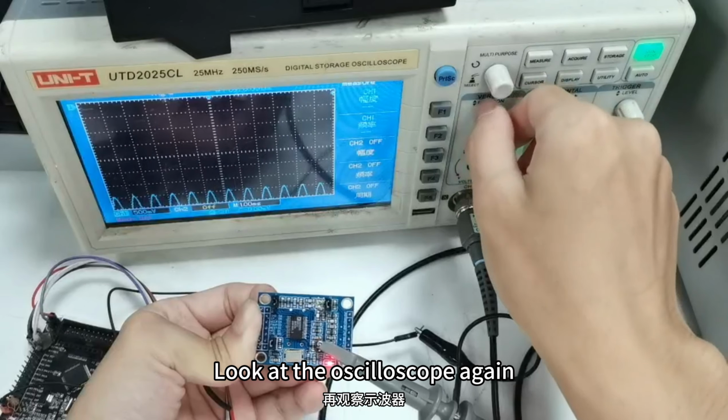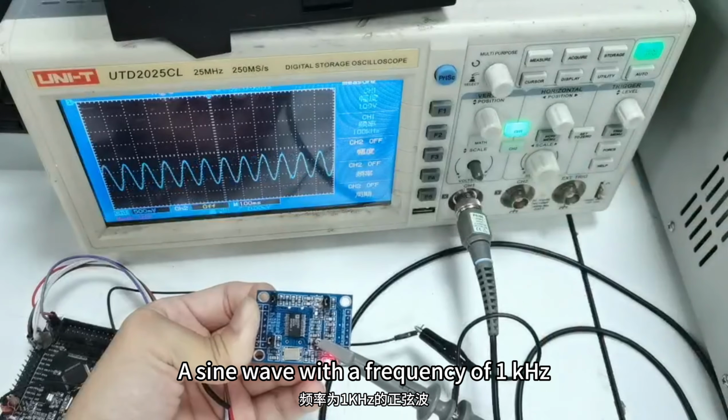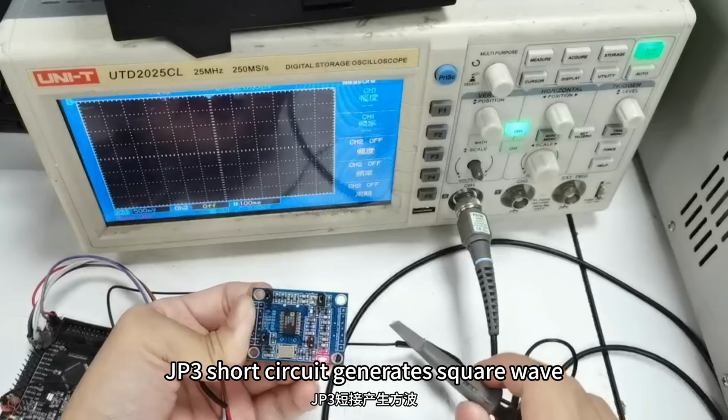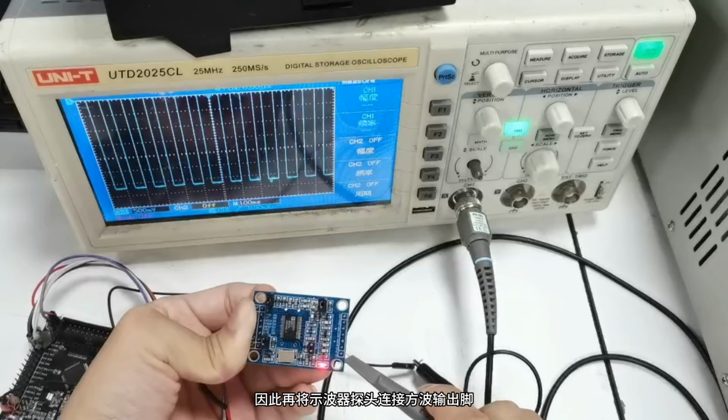Look at the oscilloscope again. The observable amplitude is 1.2 V. A sine wave with a frequency of 1 kHz. JP3 short circuit generates a square wave. Therefore, connect the oscilloscope probe to the square wave output pin.